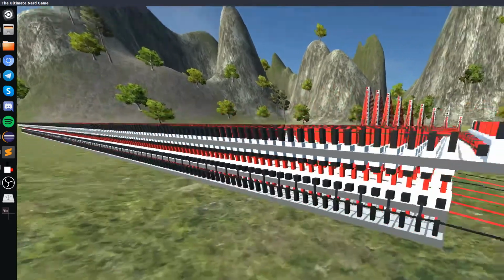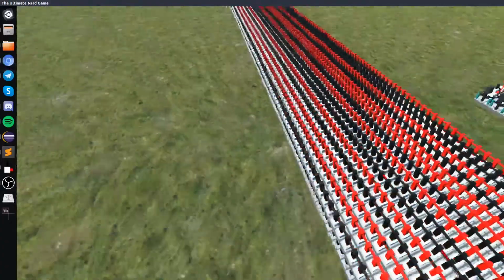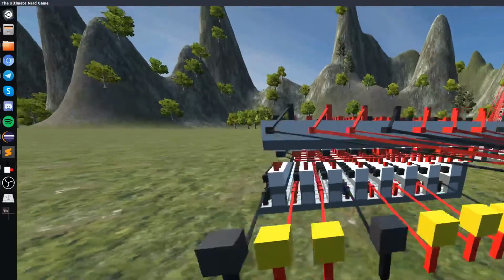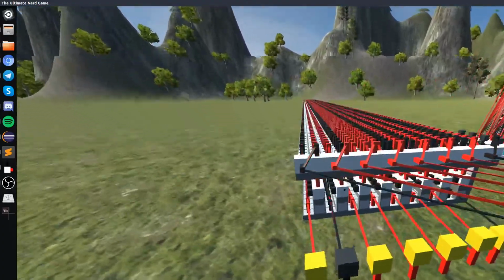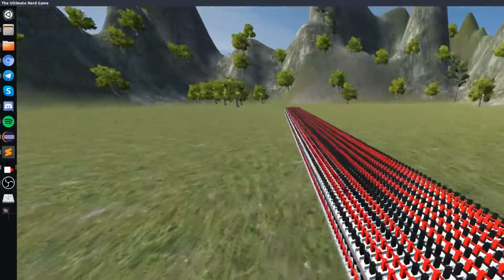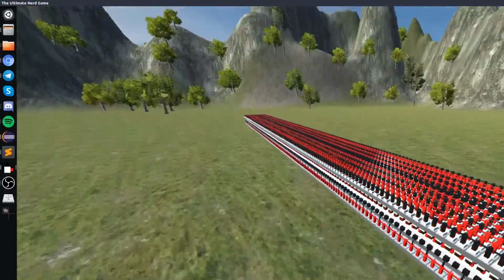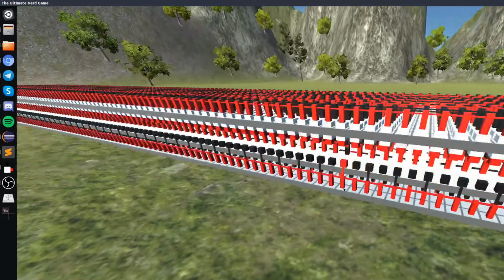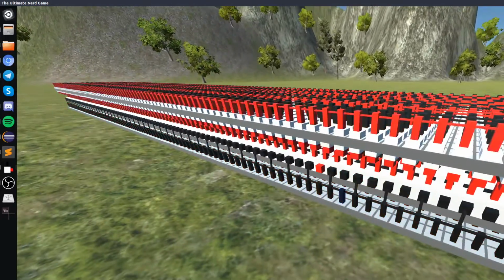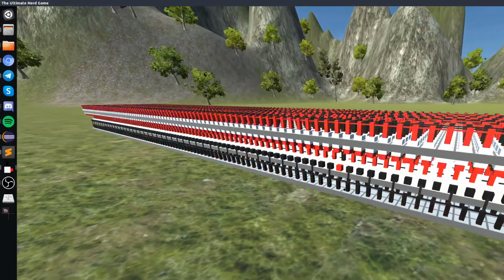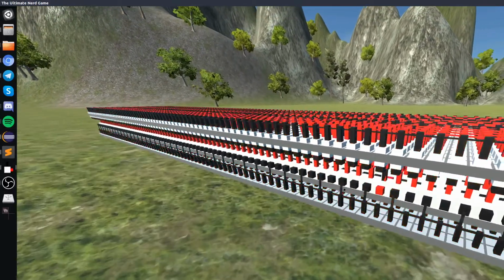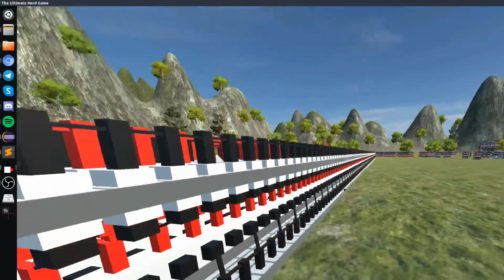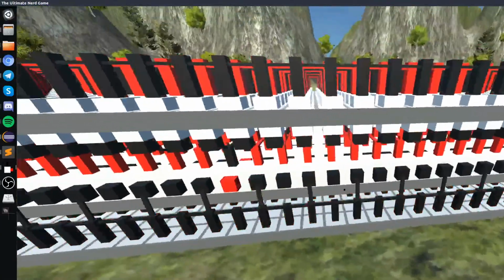This is a big bad ROM. It's 8 bits in 2 blocks wide per bit, and it has 256 addresses. Yeah, it's super tasty. You can see how the current active address walks to the end of it. And if a wire is set here, the current bit will be sent to the output. If not, that's a 0 bit.